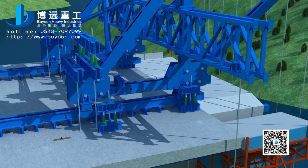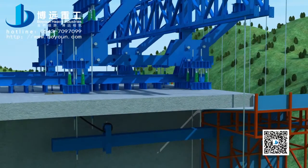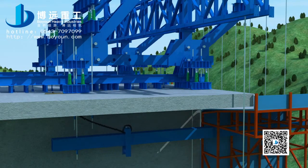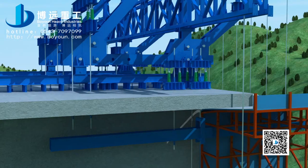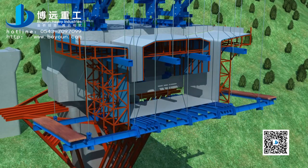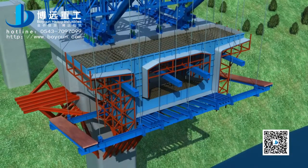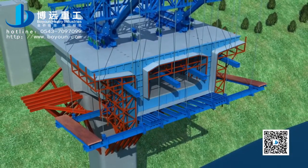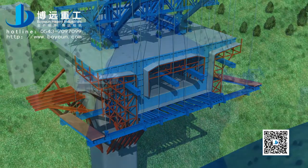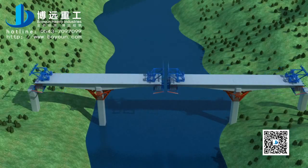Reinstall bearing hanger rod. Use bearing plate to anchor internal and external nose girder and move the nose girder's rolling hanger frame to the specified location to anchor. Adjust the bottom support system and overall framework elevation. And begin to cast the next section concrete. Circular like this to complete the construction of the remaining cantilever section.